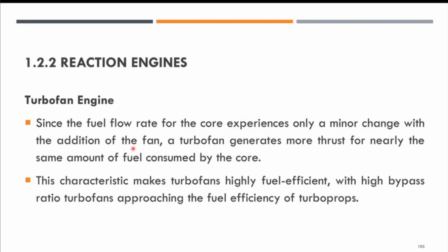Since the fuel flow rate for the core experiences only a minor change with the addition of the fan, a turbofan generates more thrust for nearly the same amount of fuel consumed by the core. It is normally known as highly fuel efficient compared to the turboprop engine.